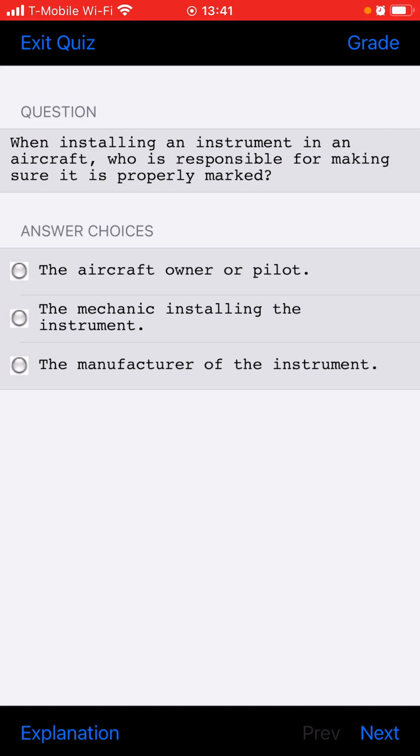What procedure should be followed regarding gaskets and seals when replacing fuel system components? All gaskets and seals should be replaced with new ones.